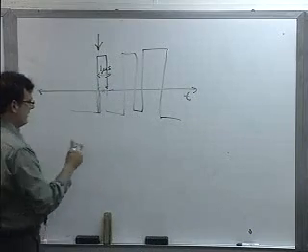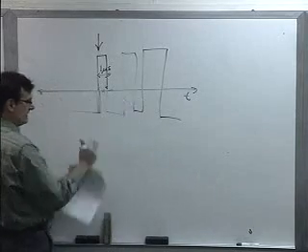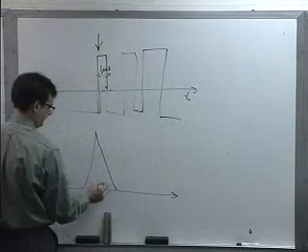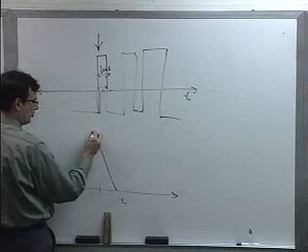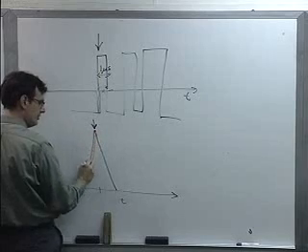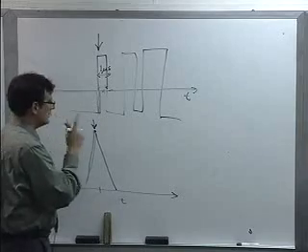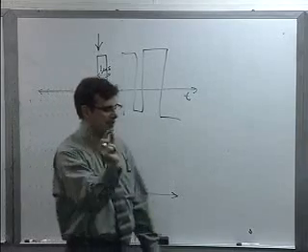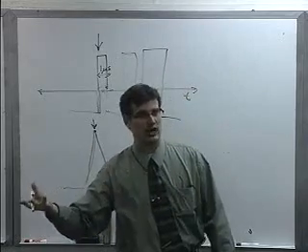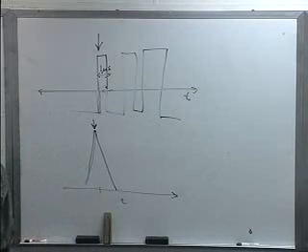But of course, if you correlate this, you remember from your last homework what the correlation spikes look like? You correlate this thing, and then there's a noticeable peak in time when you do the correlation. And if you try to key off of that peak, you need a clean signal, but you can do a lot better than just 1,000 feet. So intuitively, we know that the chip size is going to appear in a rigorous formula that translates signal parameters to position. And there's actually a very rigorous way to do this. I'll just present the result here.